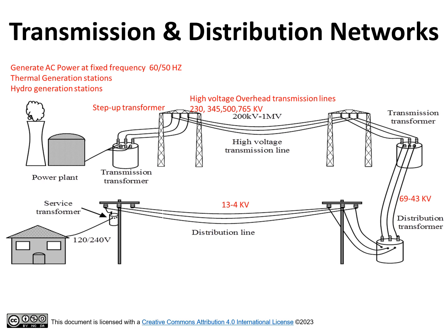Step-down transformers are used to step down the high voltage to sub-transmission level or medium voltage transmission, in the range of 43 to 69 kilovolts. Distribution transformers reduce the voltage to a low voltage distribution level ranging from 13 to 4 kilovolts.